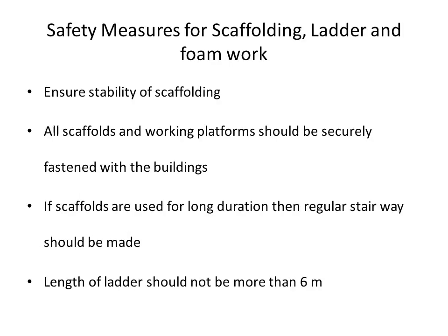So next is safety measures for scaffolding, ladder and formwork. First of all, we have to ensure the stability of scaffolding. Every scaffold should be securely supported and properly braced to ensure stability.